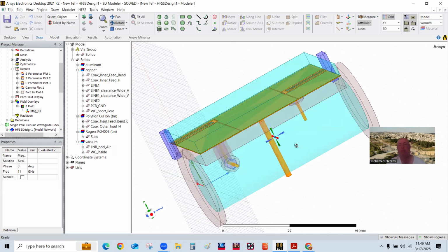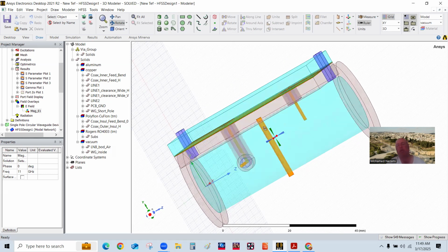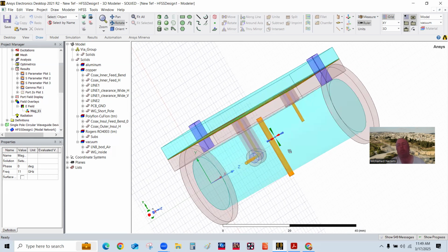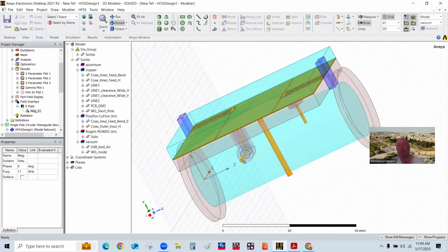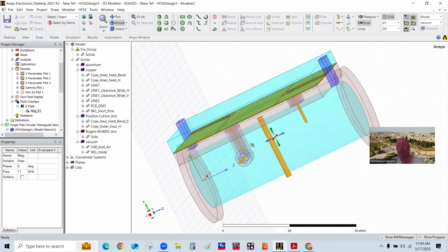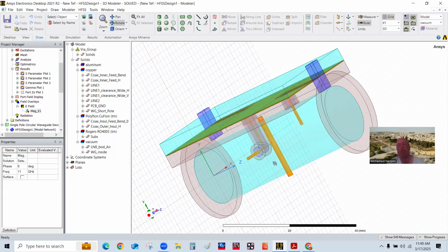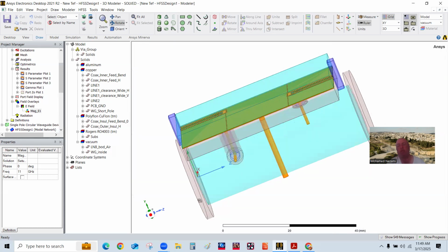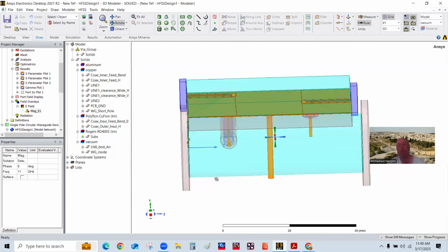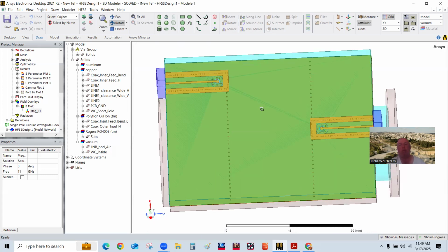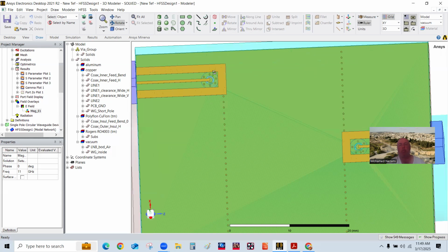Now the horizontally polarized signal doesn't get impacted by this metal pole, so it goes down and gets picked up by this horizontal pin in here. Again, this one has a back short in the waveguide. If anything passes through, it will come back, and both get pulled up to the board, where I had